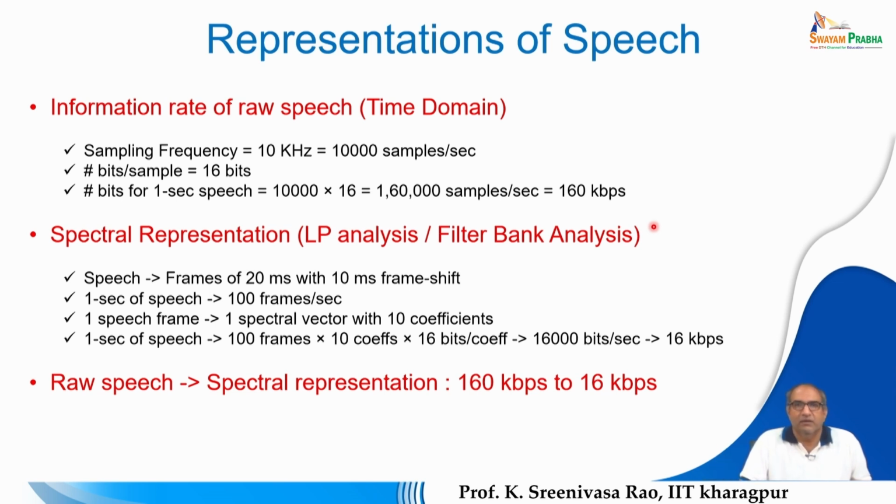So we have already come across the concept of a vector, whereas the individual component can be viewed as a scalar, but all these 16 scalar values put together form a vector. Now this vector quantization is related to quantizing the spectral vector, or quantizing the vector on the whole. It is not with the individual values. That is the difference between scalar quantization and vector quantization.